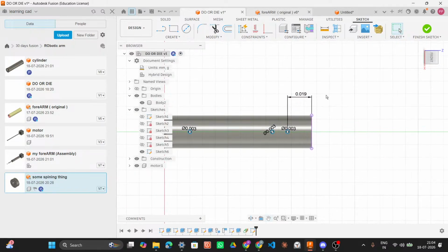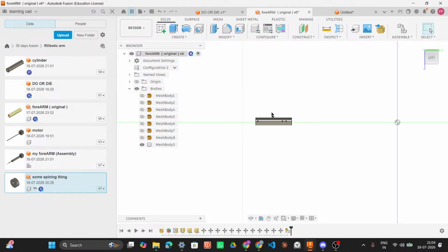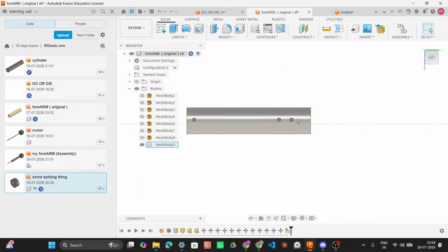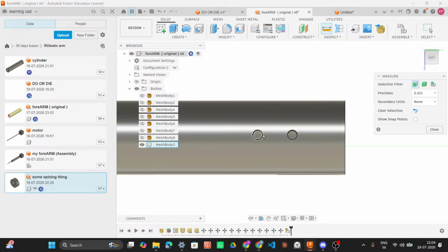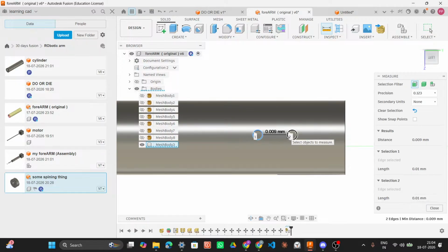So this is that, yeah. Like that file that you had where it did the conversion wrong and you just had parts of those holes and the two ends of the tube, that would be plenty to get a sketch reference off of, and just rebuild the part from scratch.